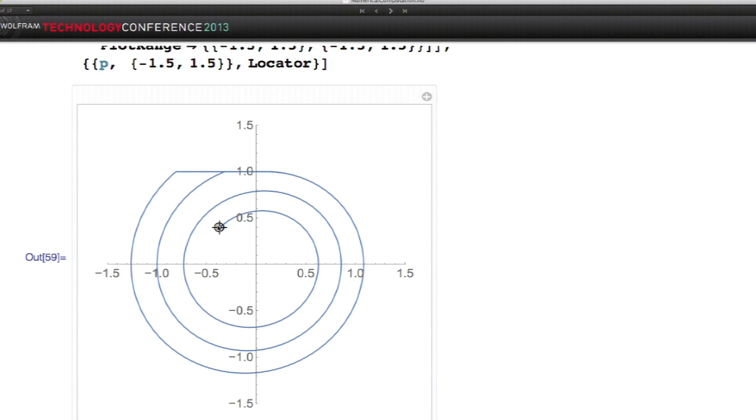And I gave it a discontinuous vector field. So basically the vector field here is pointing up, and the vector field here is pointing down. So everything gets sandwiched into so-called sliding mode along that. Now, without being able to detect the root of that crossing, which NDSolve now does automatically as of version 9, we wouldn't get anything for this system.